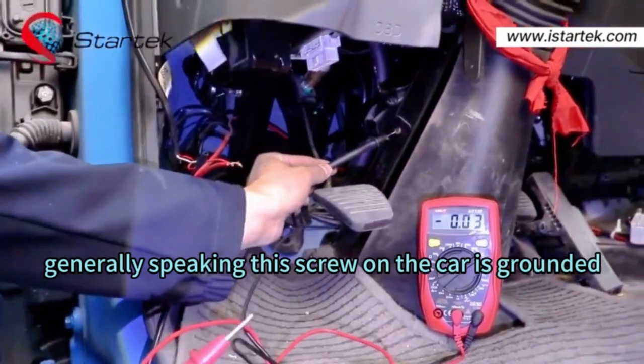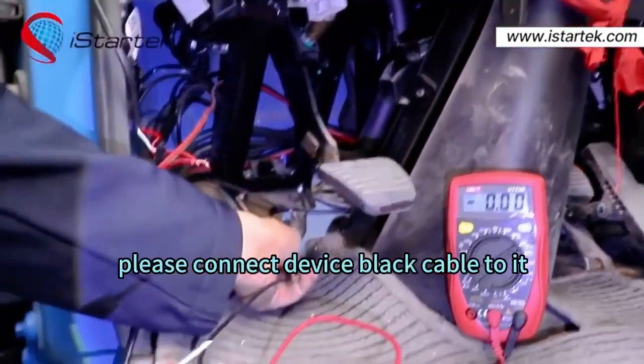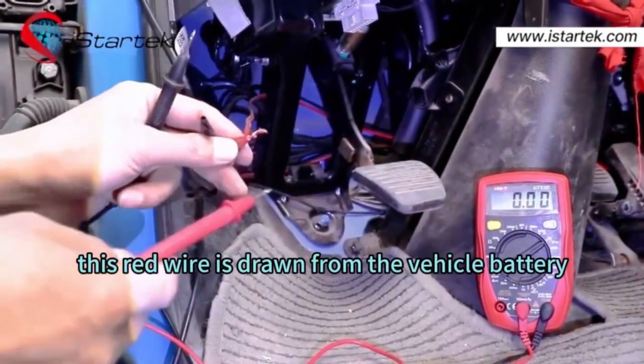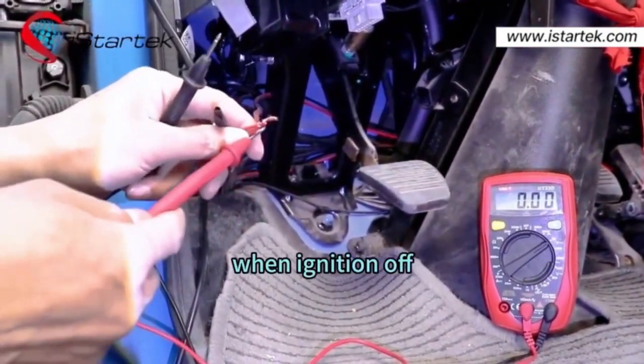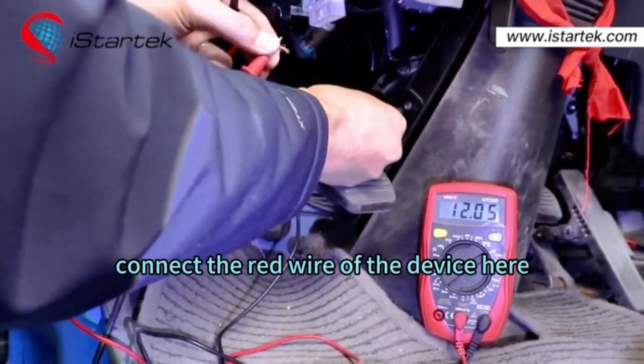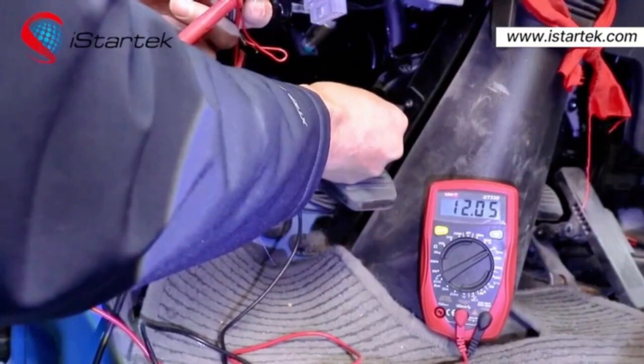Generally speaking, this screw on the car is grounded. Please connect the device black cable to it. This red wire is drawn from the vehicle battery. When ignition is off, it still has the same voltage as the vehicle battery. Connect the red wire of the device here.